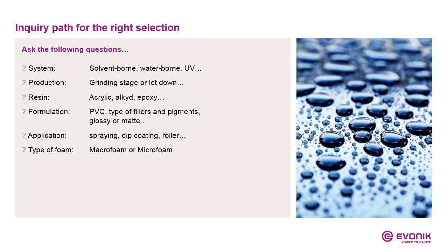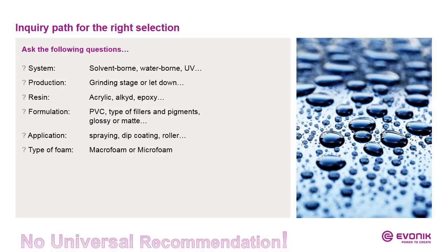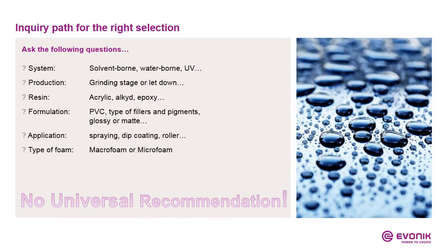And what's inside the formulation also matters a lot. For example, the types of the fillers or the pigments, whether it's a glossy or matte, it all matters. What also has an influence is the application, just like I showed you in the previous slide. And depending on the foam type, whether it's a macrofoam or microfoam, you have to use either TEGO Airex or TEGO Foamix. Therefore, we can conclude that there's no universal recommendation that works in every single formulation.